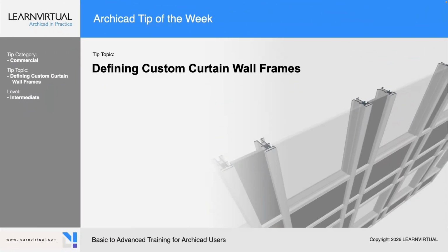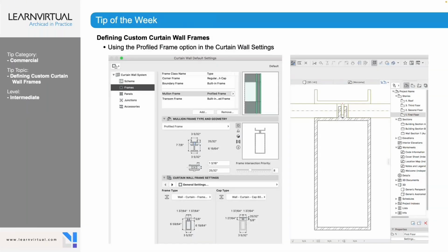Today's tip of the week is how to define custom curtain wall frames. One of the advantages to curtain walls is that you can define very custom frames as part of that. It could be a cap, it could be the frame of the actual curtain wall. As you can see here, here's our cap, here's our curtain wall frame, and those can be defined as presets